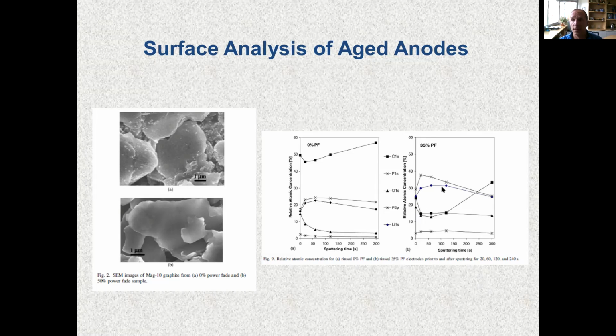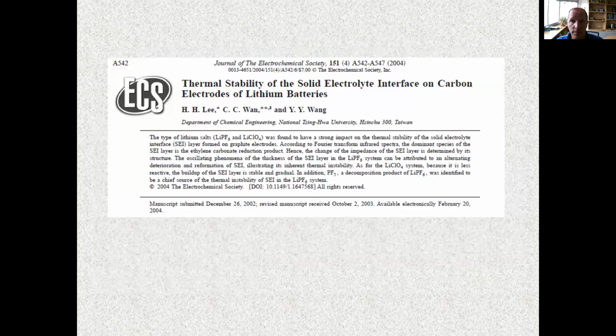And so once again, what we'll see in the lecture tomorrow, or the next presentation, is a detailed mechanistic investigation of how this evolution of the SEI occurs, and then also how you might be able to stop it. So another investigation by Professor Li at the National Taiwan University, what they were able to observe was that in LiPF6 versus lithium perchlorate, you see an evolution of the SEI, where you see SEI degrading and reforming and degrading and reforming in the case of LiPF6, which you don't really see with lithium perchlorate.